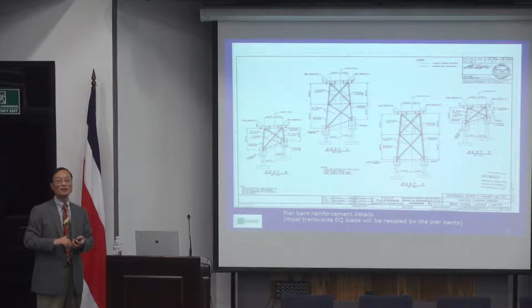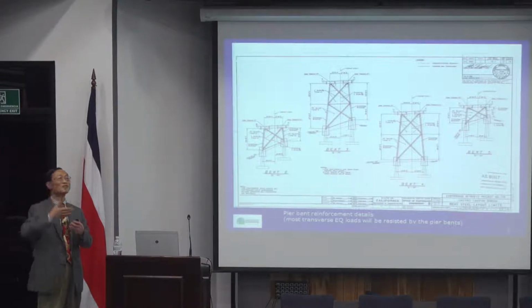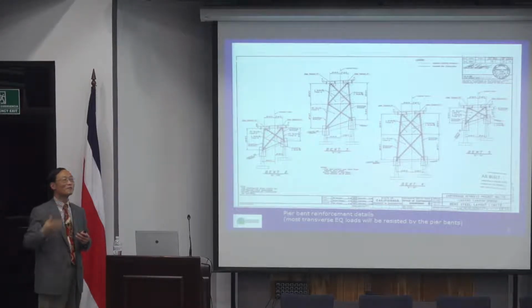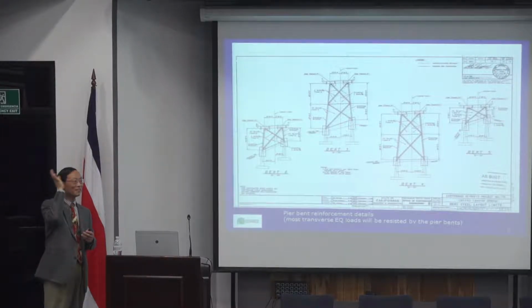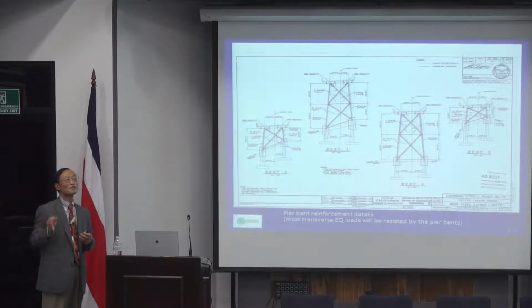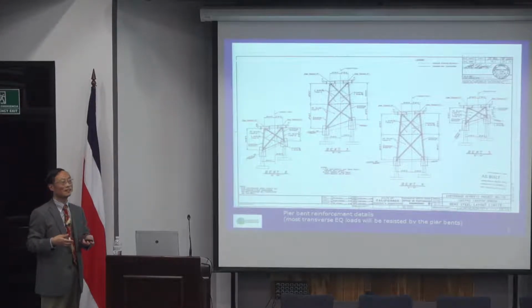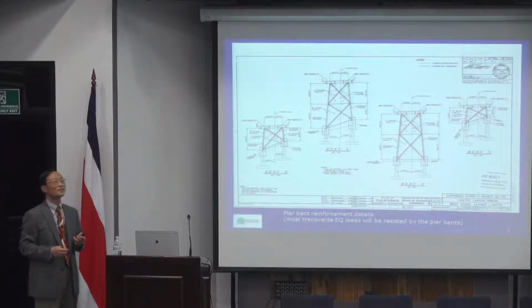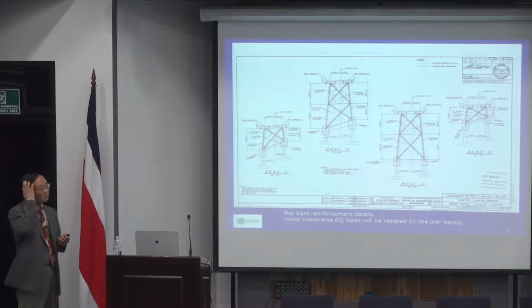We all know there's a bridge that failed in Minnesota. The Minnesota bridge, of course, that's gusset plate. Gusset plate is typically designed for in-plane actions, but in reality, the gusset plate has other links. So it has introduced a perpendicular force, which is in a very weak direction. That causes a lot of stress and deformation, and that is part of the reason it collapsed. There are many, many reasons, but that's just one of the reasons.